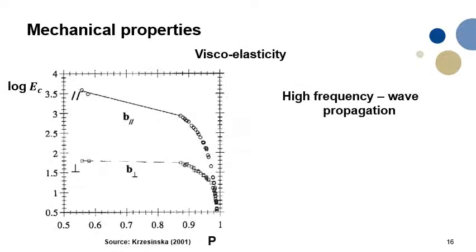About high frequency, a linear relation seems to be true in the flexible graphite region of densities here. It's still the same as in the low frequency, because increasing the porosity means decreasing the density. So increasing the density in this direction means increasing the storage modulus.